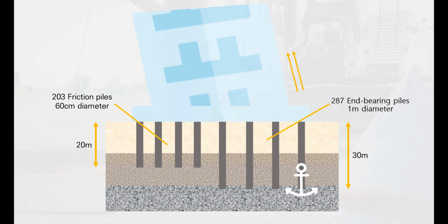These piles are in tension due to the massive eccentric overhang of the building. It may sound quite awkward that they used different lengths and diameters of piles, but it is actually a really efficient way to make a foundation for the world's most leaning tower.